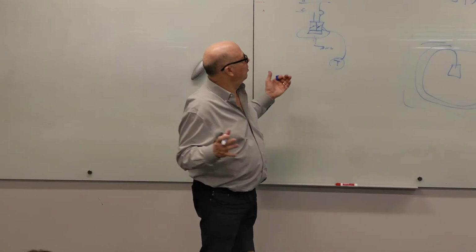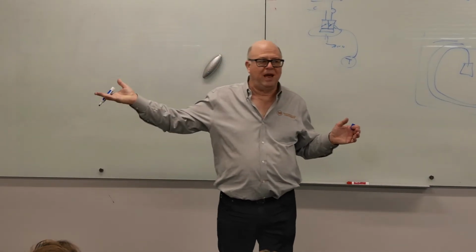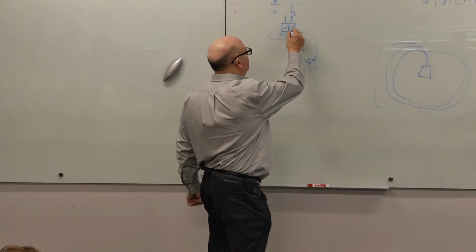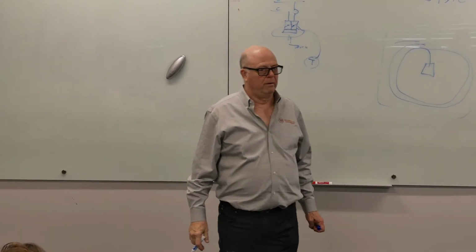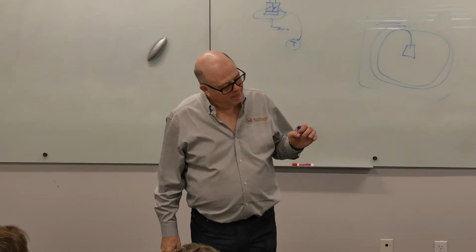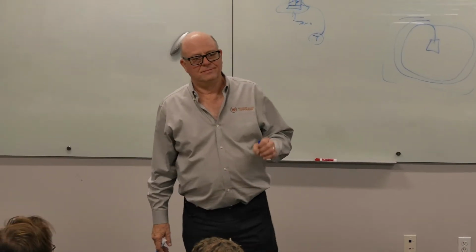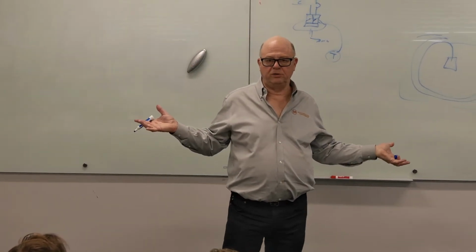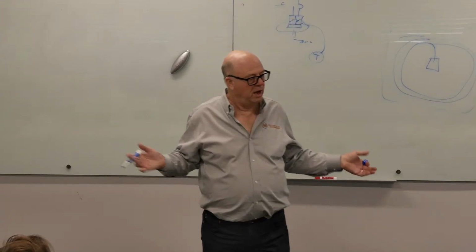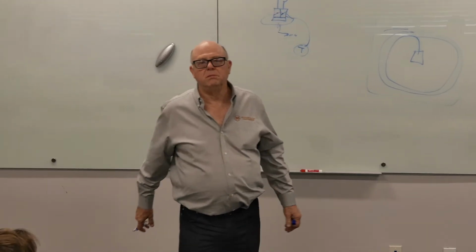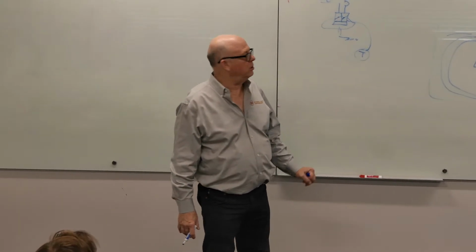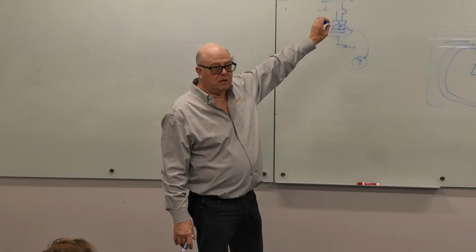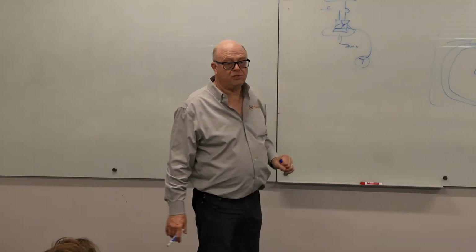So what do you do if the room is happy the way it is and it doesn't need any air at all? Well, what you're going to end up doing is giving it usually a little bit of cooling air. Although, I mentioned earlier CO2 sensors. If you're not measuring any CO2 in the room, you can shut them both off. And there are some other things you can do. Consult with Brian. But dual duct VAV is a very common system.